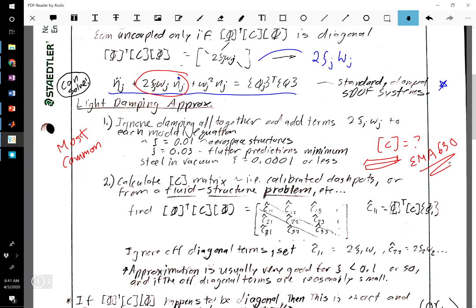For a material like steel, it's actually slipping, sliding, friction at the grain boundaries that causes the damping. Though people have done interesting experiments on single crystals at the micro scale, and then you have other effects, thermoelastic effects, and all kinds of crazy things that can cause damping.